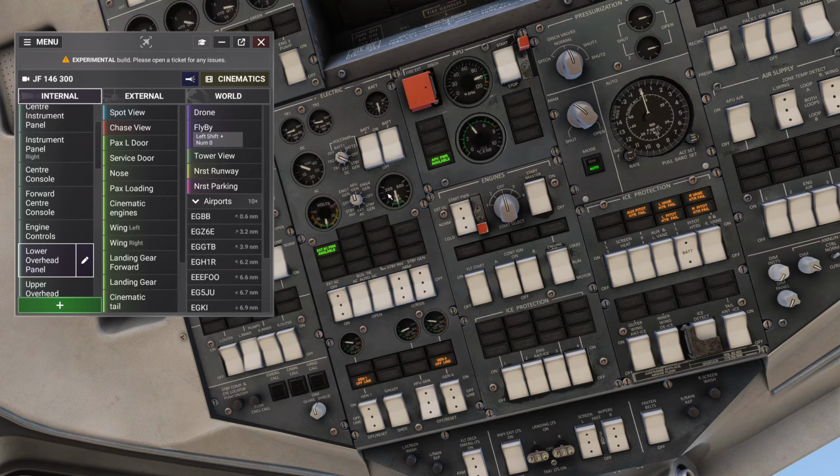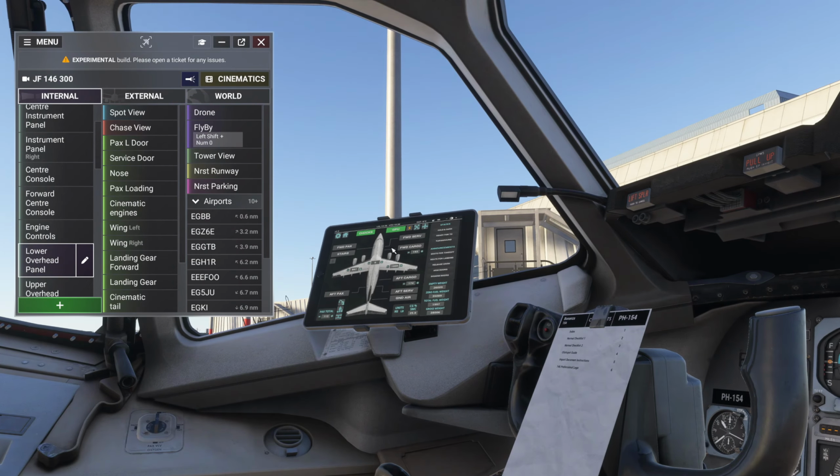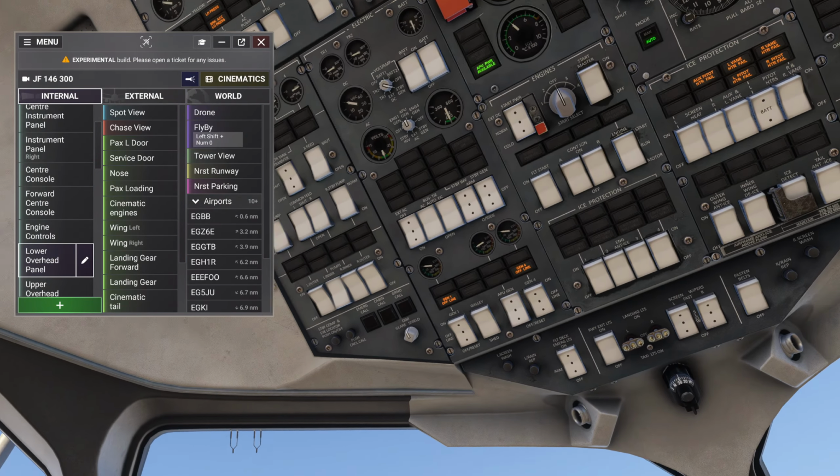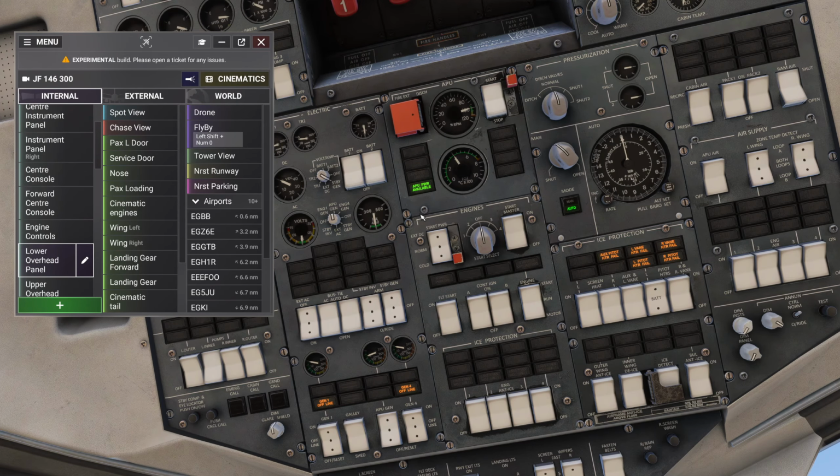Perfect. Next up, let's turn off the external power now that we have the APU providing power. Once that's done, we can move on to starting the engine and continuing with the rest of the checklist. Okay, external power is off, and I will set the GPU off also. Yes, continue please. Great, that's all set. Now we can proceed with the engine start sequence. We'll begin with the engine start master and then start each engine in turn. Just let me know when you're ready and we'll go step by step through that process.